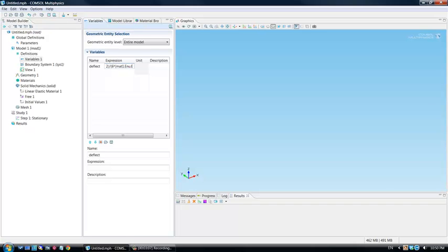This sequence here is just a way to point to where the Young's modulus is stored in COMSOL. It's under the mat1.enu section, and it's called the E value. Okay, and then I'm going to multiply by pi, and then the radius of the rod to the 4th power,